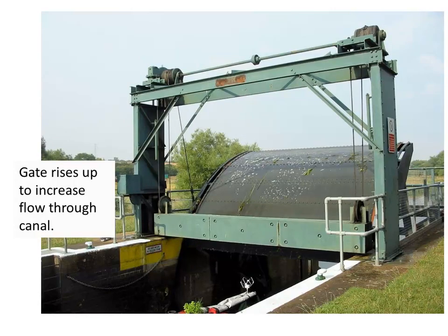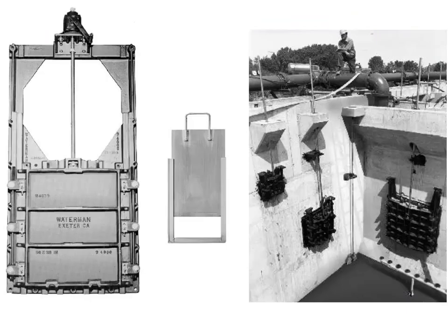And this is an example of a gate in the Netherlands that I'll just dim the lights a bit to make it a little bit more clear. Rather than having a flat surface, this gate has a curved surface, you can see. And it actually pivots about a radius, and the purpose for that is that it makes it easier to lift and lower the gate because the hydrostatic forces push through the center of rotation rather than in any of these flat gates, the water is actually going to be pressing the gate up against the frame and increasing the difficulty of opening it.